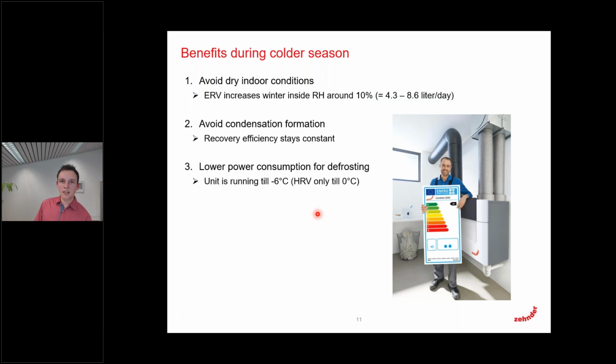Another important point is that the ERV is running till -6 degrees. The HRV, in comparison, is only running till 0 degrees. This is due to the recovery of moisture and heat. Below these temperatures, you would have the risk that the unit is freezing, and this leads to damage to the unit. To avoid this, we have an additional preheater. So if you are in a cold region, you need a preheater.